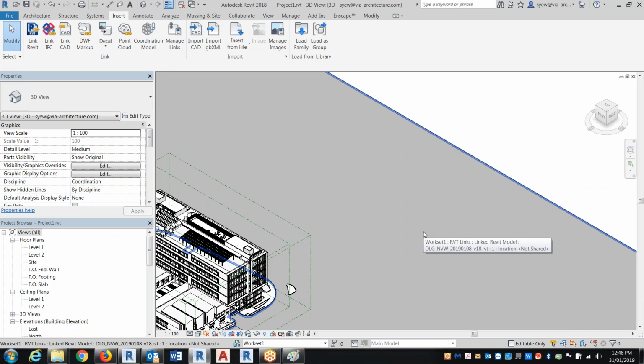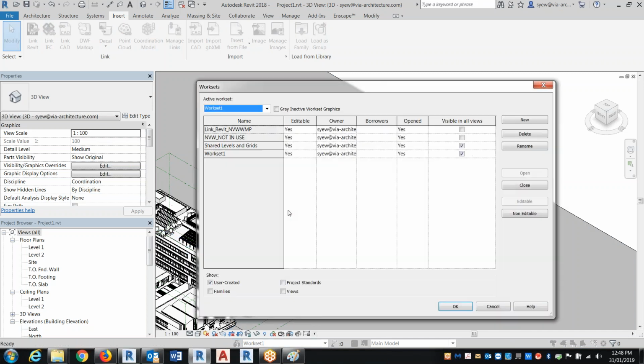So if you want to have consultant files and you do not want to show a lot of the stuff, have it the same. I always tell the users, if your workset is going to be named this, can you add an acronym from the beginning? Let's say their dialog, DLG, just add it to all the worksets so that you know it's from dialog. So in most cases, if you're working with multiple consultants, different people have different naming conventions. This is something that has to be discussed in the beginning so that you get consistency on who's using what, right?